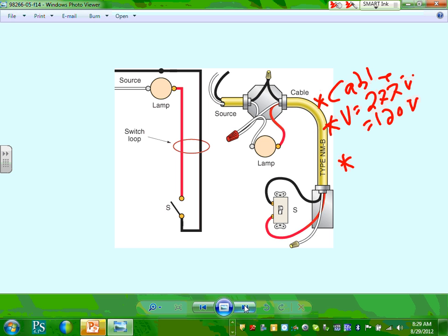So these are basically lights and switching. You're switching lights, not motors, not air handling units. Well, not garbage disposal. Then to apply the exceptions. The exceptions: if you have access to the box from the back, the front, the top, or the bottom, then the exception applies. I guarantee you a lot of people are enforcing it across the board now. Any comments, any questions about neutral with the switch, snap switches?